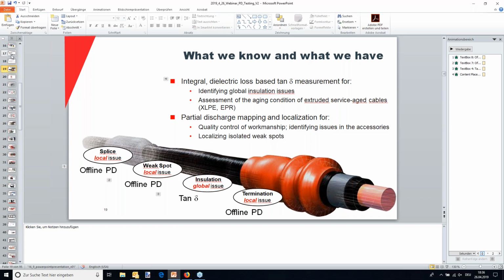Thank you. The next question is: as far as I know, PD trend value is important and not PD absolute value, so how can we test cable through PD absolute value? The absolute value is quite important because you calibrate the circuit, and that's the whole trick with this IEC circuit, that it is the only calibrated PD measurement. Because if you have PD below the background noise, then it's important to know you're not measuring that, because that magnitude is hidden in the background noise.